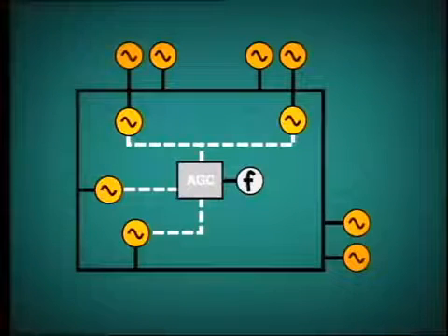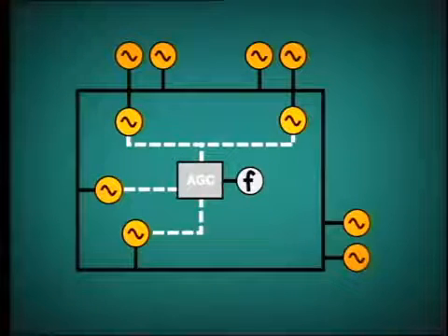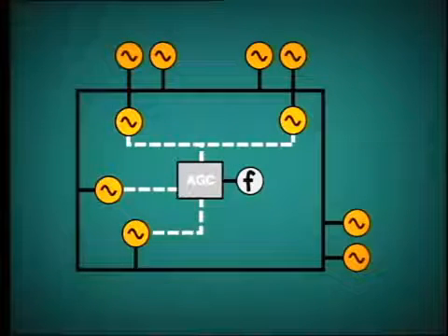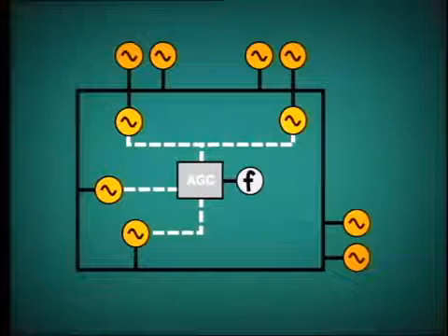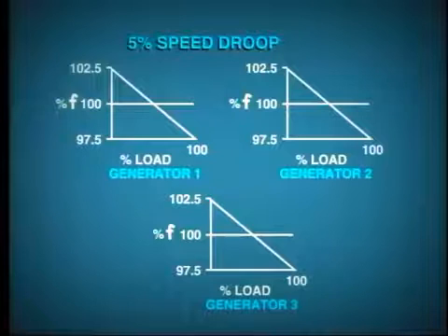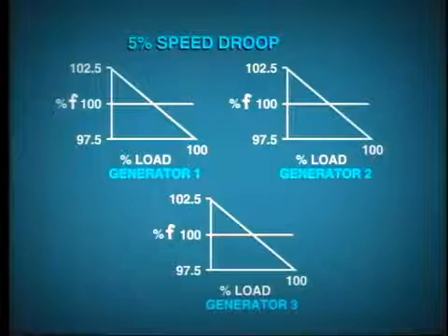Usually, certain generators on the system are selected to operate as regulating units, receiving immediate signals from the AGC system to correct frequency. The objective of the speed droop setting is to ensure stable operation of generators which are connected in parallel on the power system. If all of the governors on the synchronized generators are set to, say, 5% droop, then they all share in load changes proportionally.